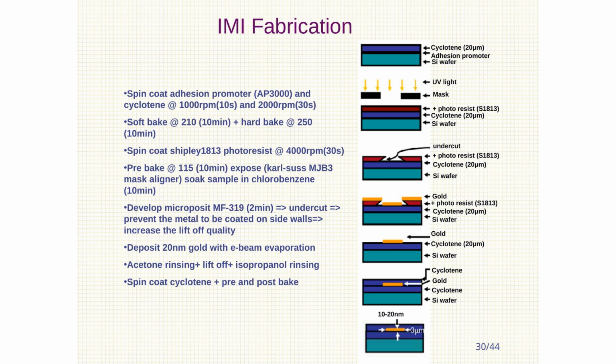Photoresist S1813 is spin-coated, pre-baked, exposed, and developed to achieve undercut, enhancing lift-off quality. Gold is deposited via electron beam evaporation, followed by acetone and isopropanol rinsing.